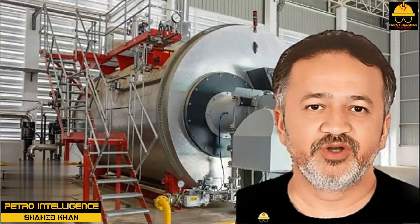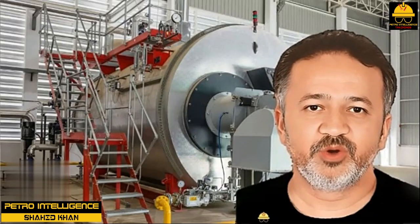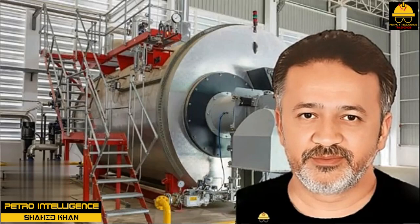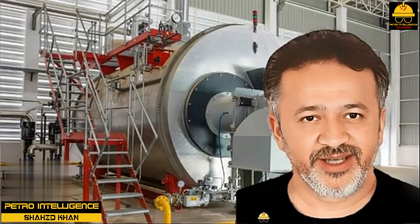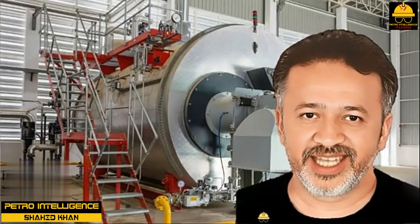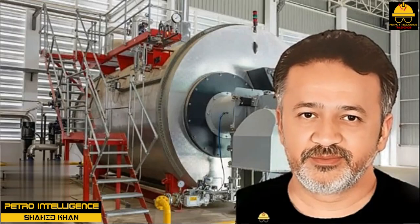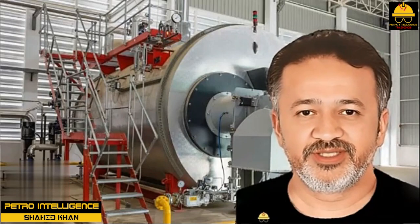Some plants collect all their contaminated steam condensate streams from reflux drums and from a vacuum tower hot well system. Without even steam stripping, the collected condensate is recycled back to the steam boiler. It's true only where low pressure, 100 psig, steam is generated. It's true the steam so generated is not used in a turbine or in any chemical process. But on the other hand, they had been doing this for 20 years without any ill effects. Depending on the contaminant, the condensate may be reused for a number of services.